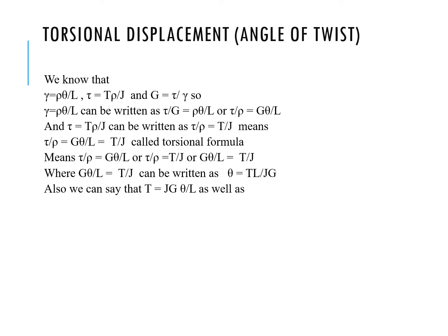On the other hand, if we have some material limitation, let's say it can produce only 1 degree angle of twist, the material is made of steel, so it will have a fixed value of G, and the material is of circular shape, so we have a fixed value of J, and we know it has a specific length like 1 meter. Then we will have the torque. This is the maximum torque the material can transfer. So these relationships are helpful for designing how much torque we can transfer by using some specific material of specific length and shape.